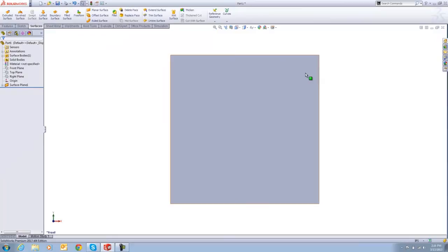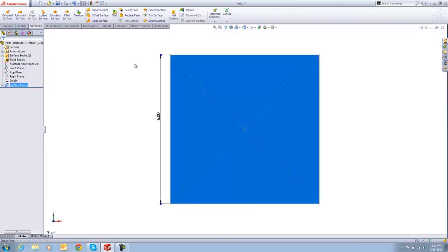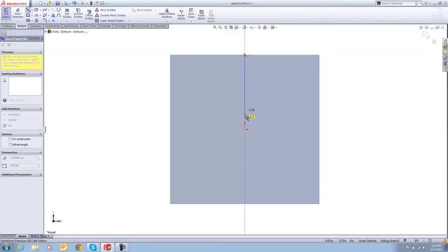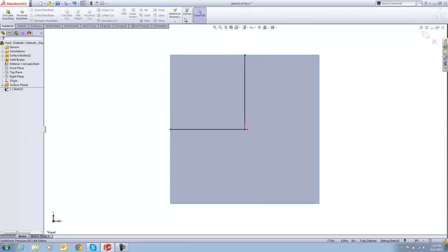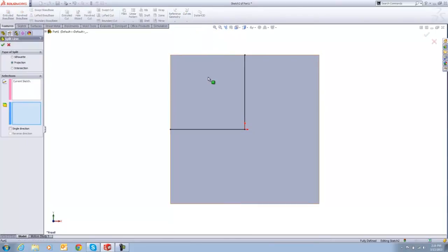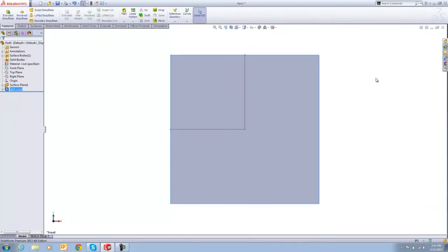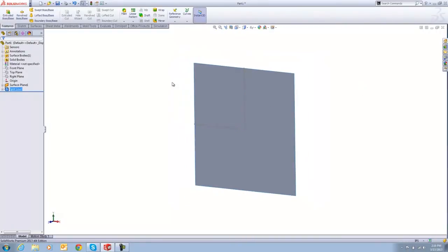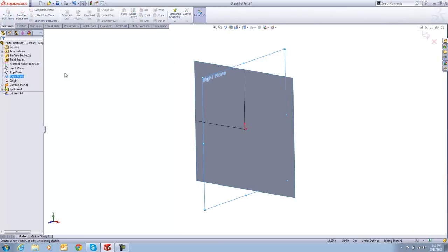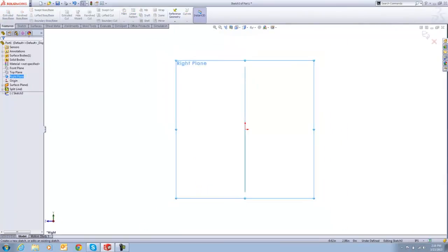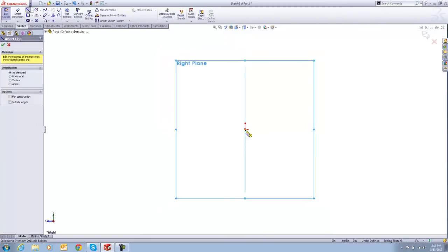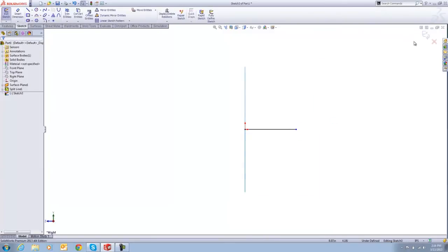Our springs are going to be applied at the center, so let's start a new sketch and use split lines to create a vertex in the center of our plates. Okay, that's one plate. I need 3 more. And for that I will create a very simple piece of reference geometry just to give me a sense of direction.